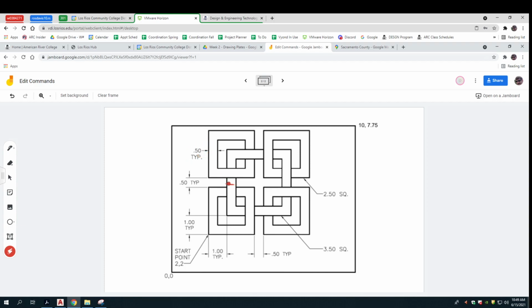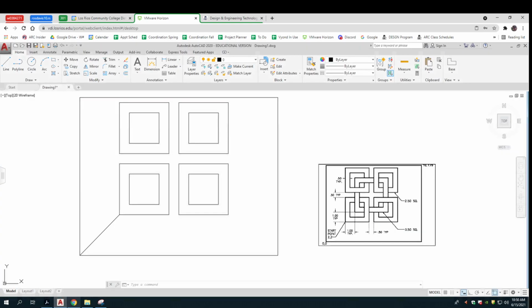So this square here is also 1/2 in. So I can make a new square, and then it says to place it from this point over 1 and up 1. So I can draw a little line to that spot, create this thing, and then move it into place. Let's try that.